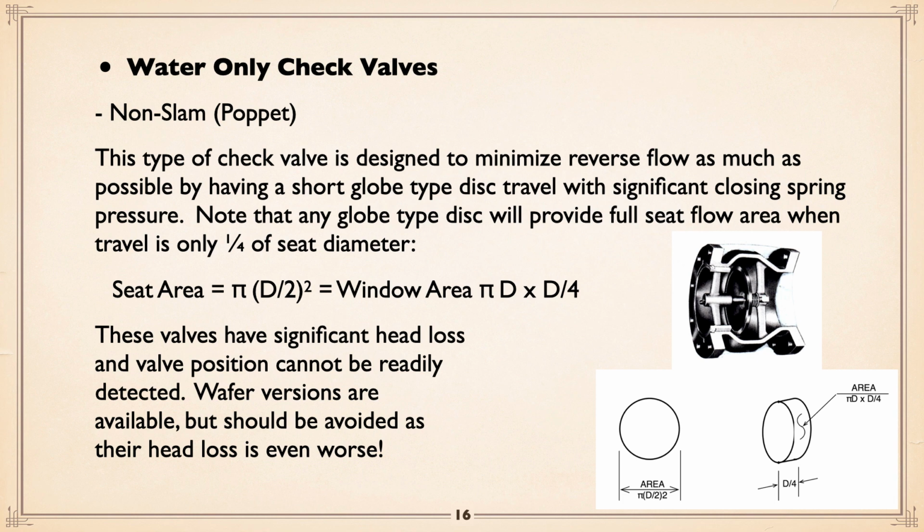The problem is that they have significant head loss, and valve position cannot be readily identified. You can get wafer versions of non-slam valves, but I would avoid them. Their head loss is even worse. It's just not the way to go.